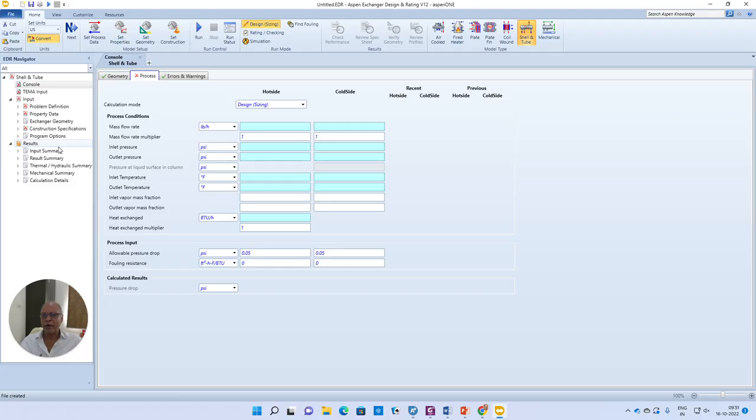But you can make a small analysis. In order to perform the energy balance, there are variables like the inlet and outlet temperatures for both the streams, cold and hot fluid. And there are 2 flow rates, the flow rate of the cold fluid and the flow rate of the hot fluid, and also the heat exchanger duty. But all these variables are not independent of each other. So you can identify the minimum number of variables that you need to specify in order to complete this problem definition.